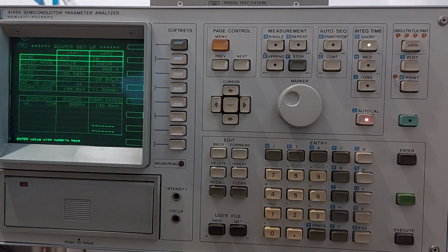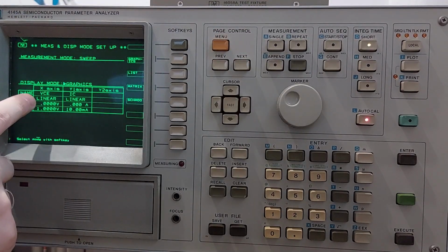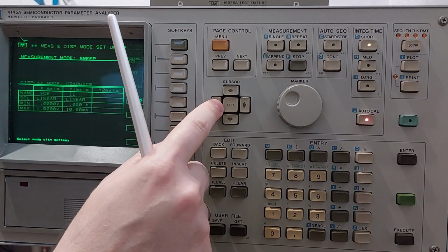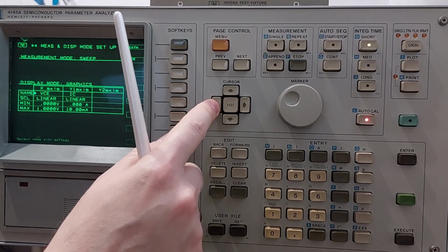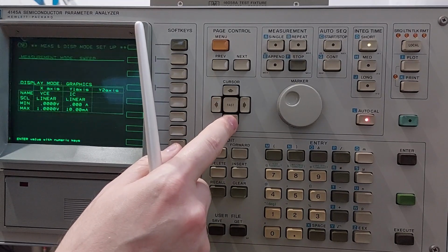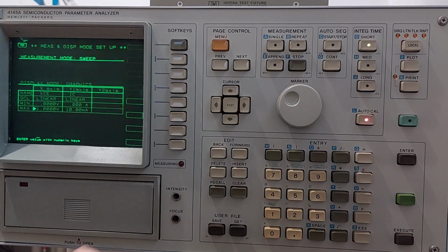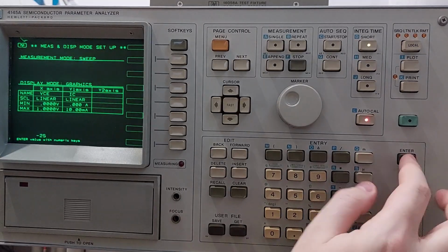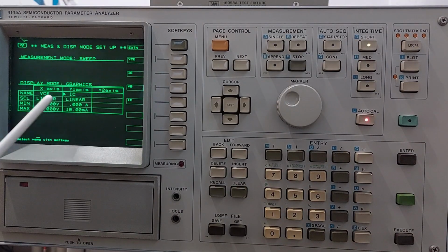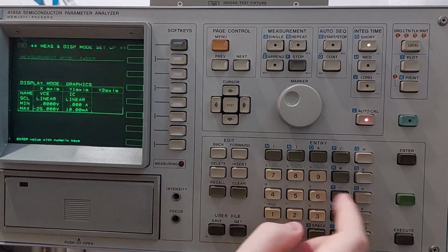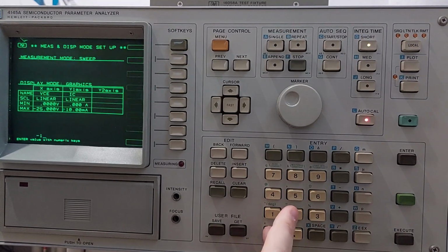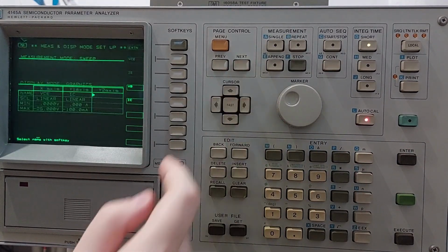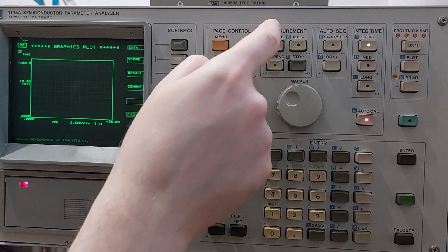So we are not changing anything else, and we press next. On this page you will define the graph limits. So I suggest you to set the same values as in previous page. For the emitter voltage we know that our limit is minus 25, so we'll set it like this, minus 25. For the collector current we know from the datasheet that its limit is minus 100 milliampere. And that's it. We press next and we press single measurements.